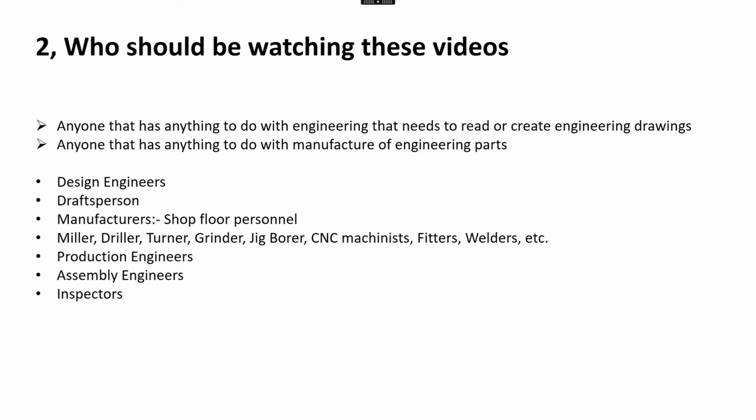This is incredibly important because if you come to jig bore some holes in a component and you don't know how accurate the roundness or the cylindricity is, or you don't know how good the position is, and so on, you don't necessarily know what manufacturing methods to use to produce those features as quickly, to the right standards and to the right accuracy. So you do need to understand the tolerances involved before doing a job, not after.